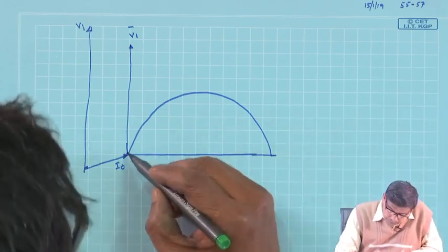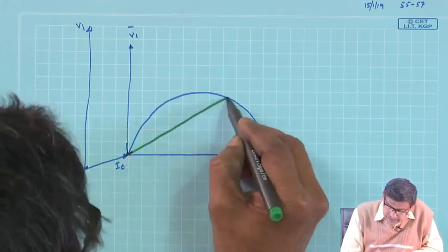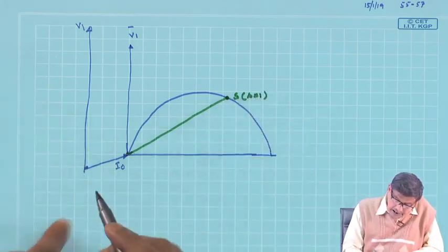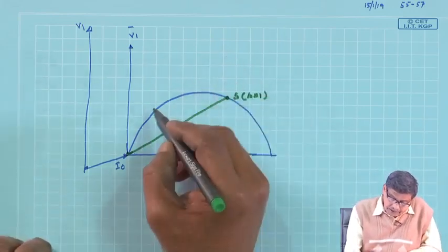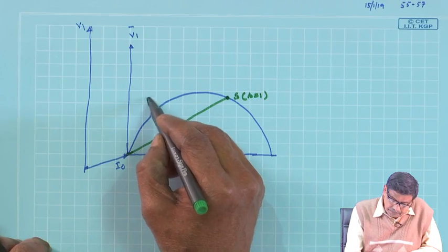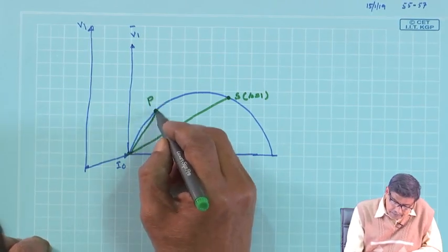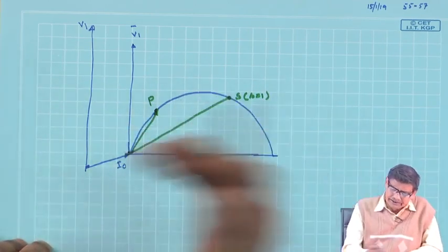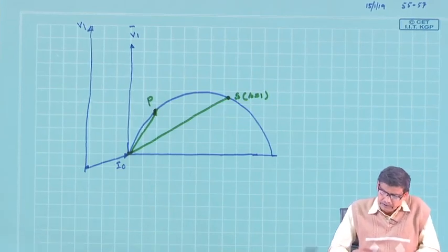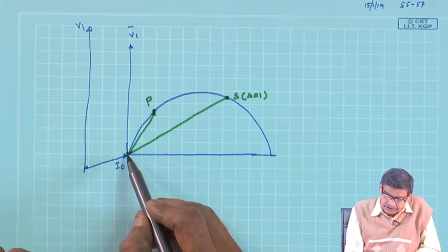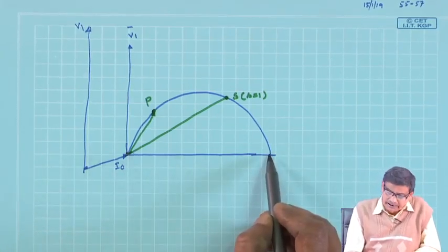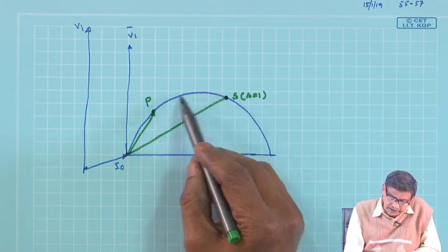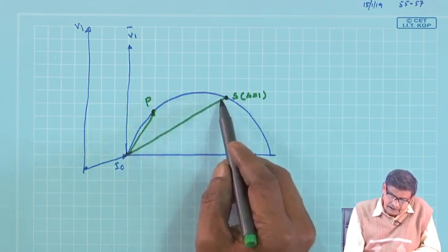There were two points, operating points we considered. One is at S equal to 1, which means the standstill condition, and another is the actual operating point, which could be lying here, P. Remember, in the RL circuit circle diagram, when R changes, I told you this is R equal to infinity and this is R equal to 0, but here R will vary from the inherent resistance, which is at this point, R increasing this way, up to the full load point.